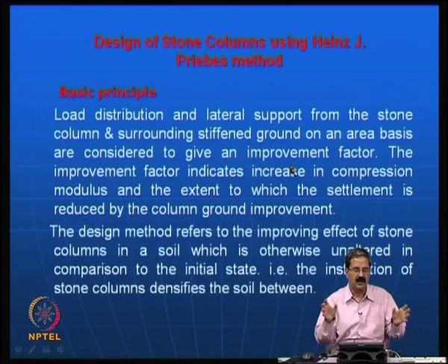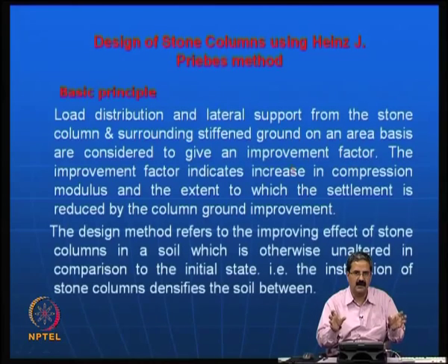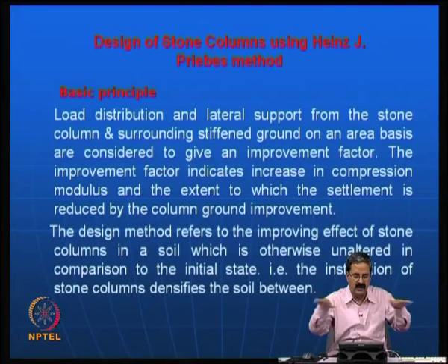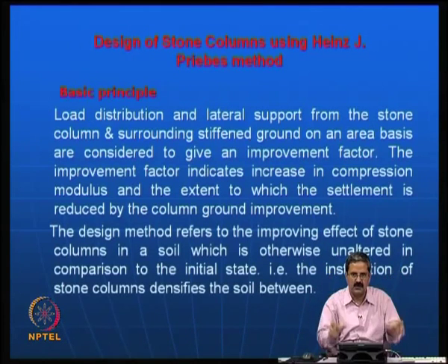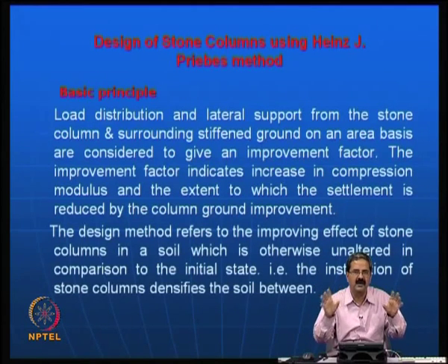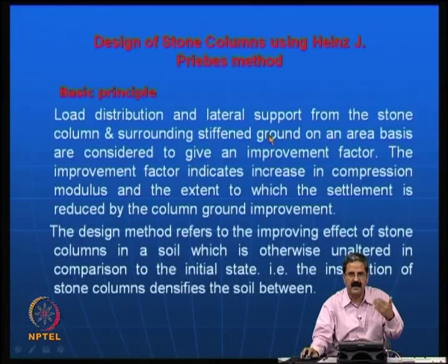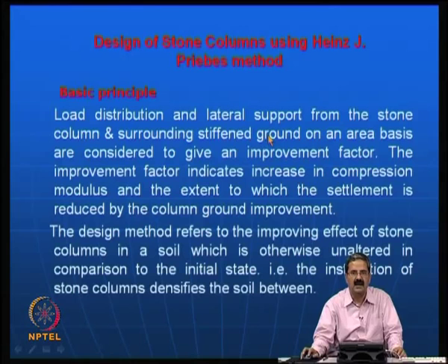Say for example, you have an actual clay soil and then you have some stone columns. Definitely you have improved the area. One can say that the improvement factor is in terms of the area replacement, how much of the area is replaced in the original soil. That can give an idea of the improvement.